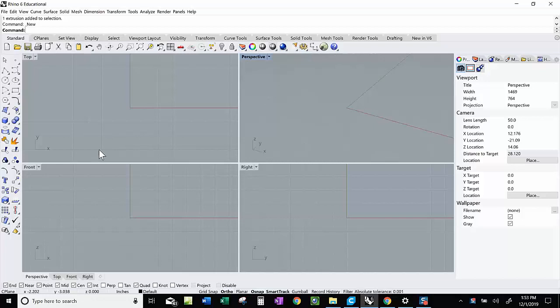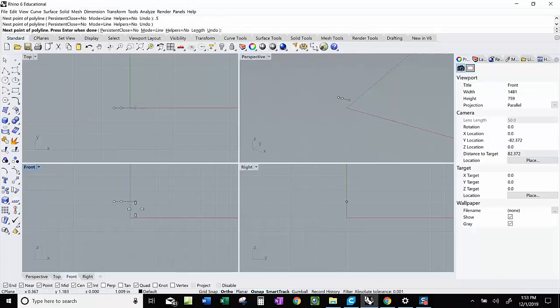And it doesn't say how wide the blade's going to be. It does say that it's about 3 inches across. I'll just make it ½ an inch wide at the end. I'll start out with the polyline, front view, got ortho on, got some object snap stuff going. So I'm going to make this, actually, I'll make it 0.5 inches long. So I just type 0.5 and then I need to click and then hit enter.